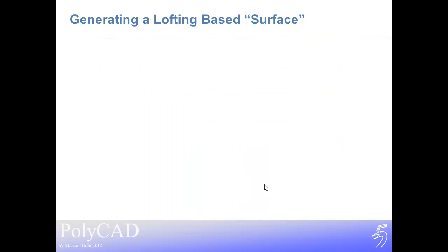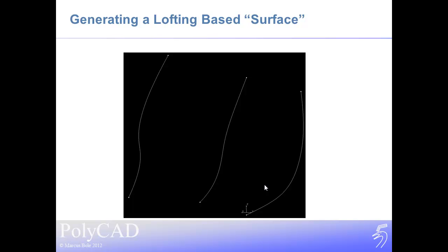So this was very much a kitchen tabletop bit of research, starting with a set of curves which we used in PolyCAD to develop the X topology surfaces. So these are X topology curves. And we simply intersect these curves using a set of planes, and for example here to generate a set of waterlines. So these are simple cubic B-spline curves using algorithms out of the NURBS book, for example, and we just throw a set of planes through these curves, get a set of intersection points and fit a curve through them.